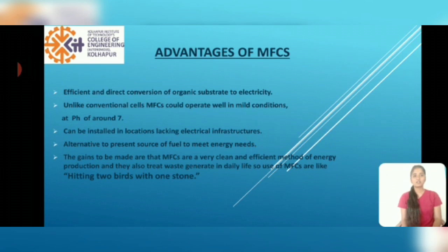We see the disadvantages of microbial fuel cells. The surface area of the anode is limited, as bacteria can clog small pores and hence limit the current. Power produced is way below that of conventional cells. The practical maximum voltage achieved is very low compared to the theoretical value. Microbial fuel cells are still not economically competitive. This can be attributed to activation losses, bacterial metabolic losses, and concentration losses. These are the disadvantages of microbial fuel cells.